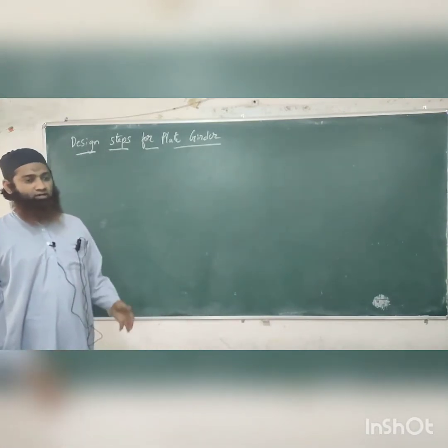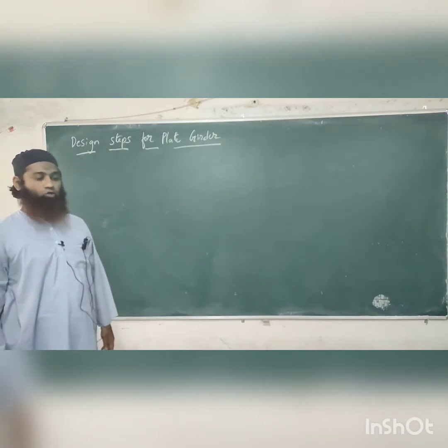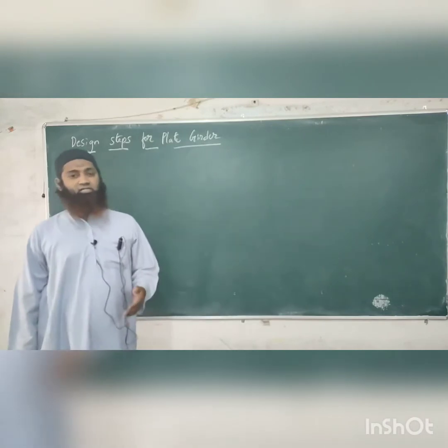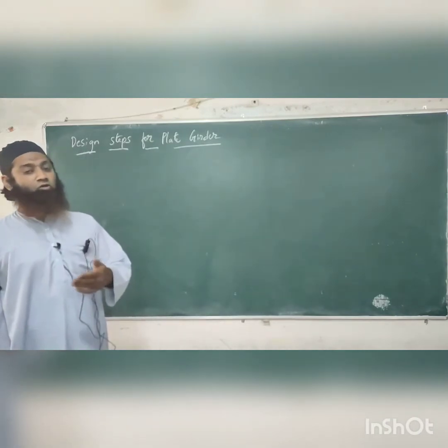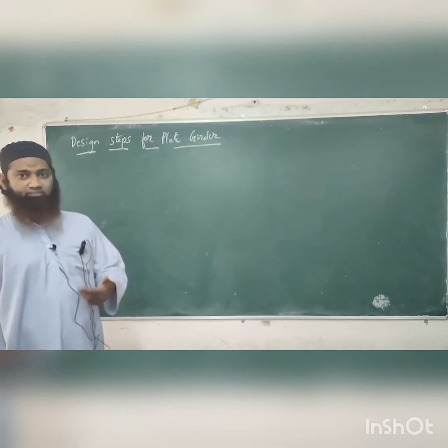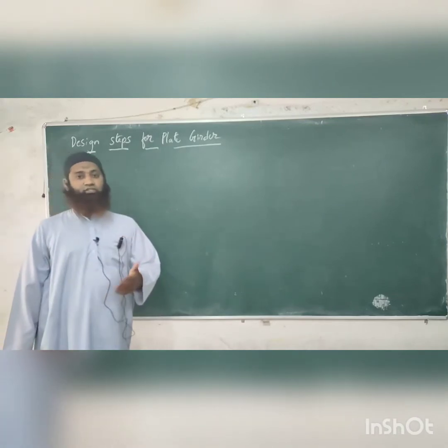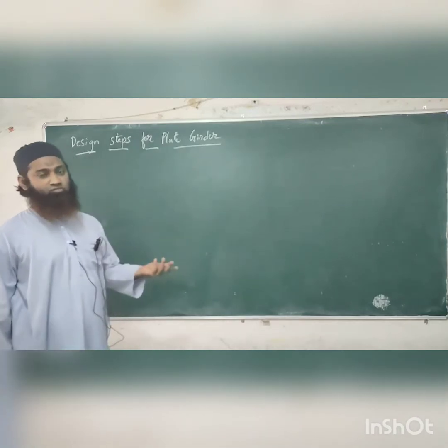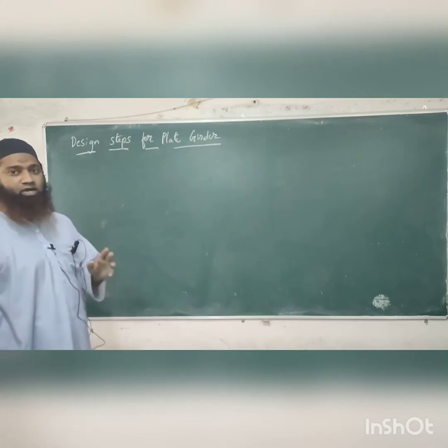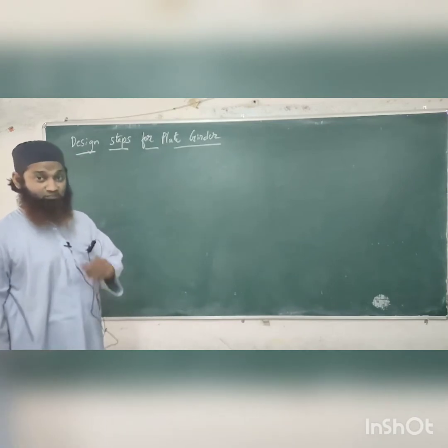Normally the load which comes onto the plate girder is a UDL, a uniformly distributed load. But in some cases there are chances of some point loads also coming onto the plate girder. So we will have to determine what type of load is coming onto the plate girder. That is very essential because the next step is related to this. So it is very important to identify what types of loads are coming onto the plate girder and what the span given here is.